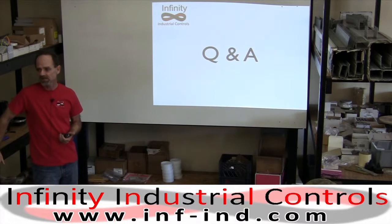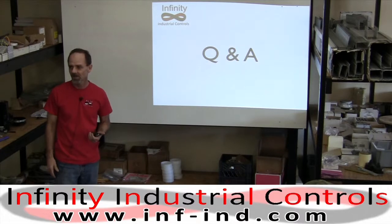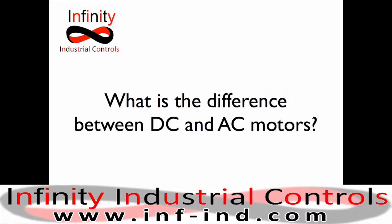Generally the speed is directly proportional to how much voltage you put on it, how much pressure you put on it. And the torque is proportional to how much current is flowing. So you can measure how much power basically by the current that's flowing through a DC motor.